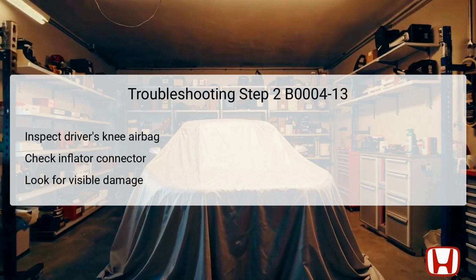If the connector appears intact, further testing will be required to determine if the airbag is functioning within normal specifications. This thorough check aids in ruling out or confirming the airbag component itself as the source of the DTC.